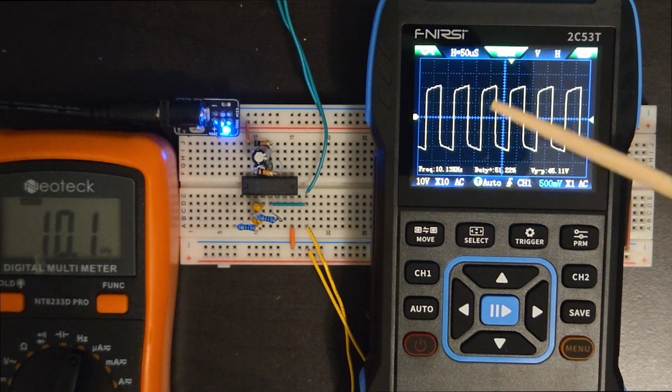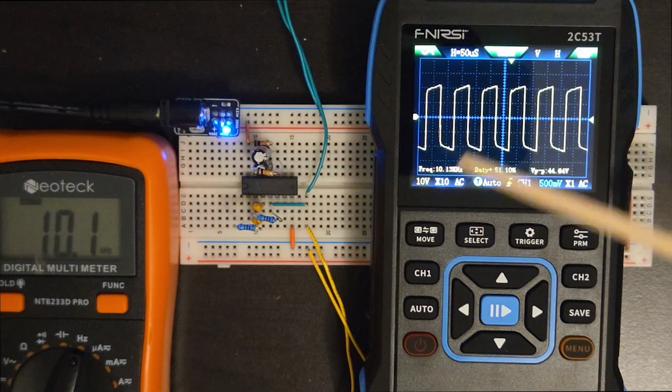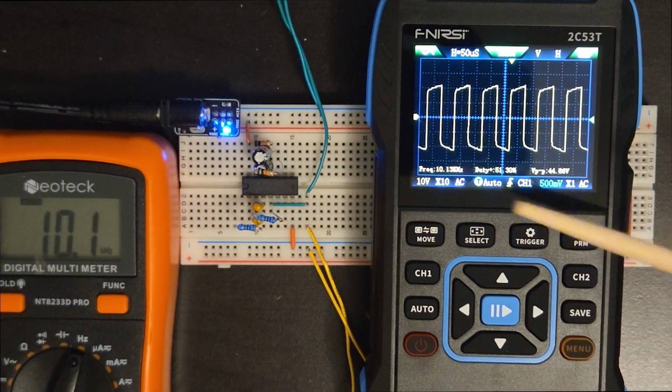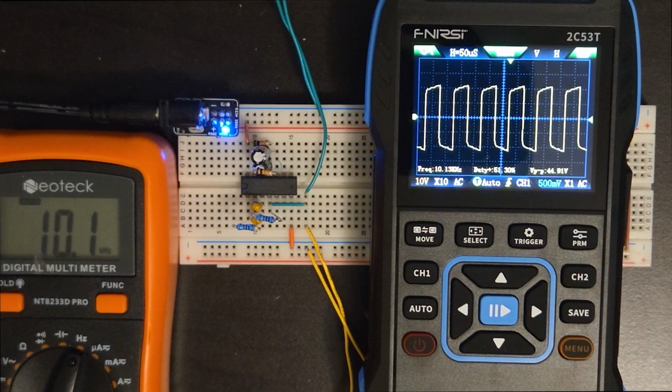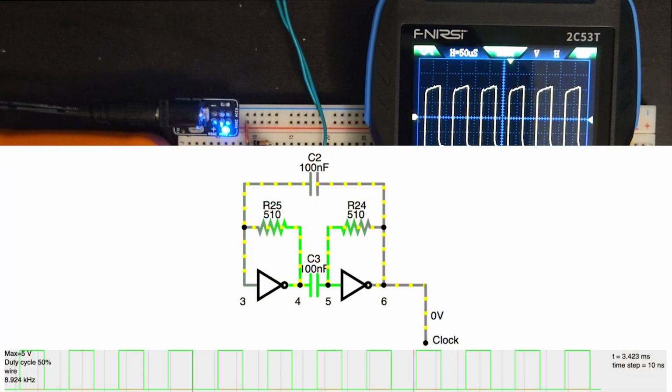And then on the oscilloscope, you can see here a fairly clean square wave, which will be ideal for cycling in our SAR ADC. As well, we can go to a Falstad diagram. This here again shows roughly 9 kilohertz. Falstad has trouble when the circuit's too fast, but that is within our accepted range. And then you can see on the bottom, the space between the lines is 51 microseconds. So the oscillation takes roughly 2 of those lines, showing that, again, it's 100 microseconds.